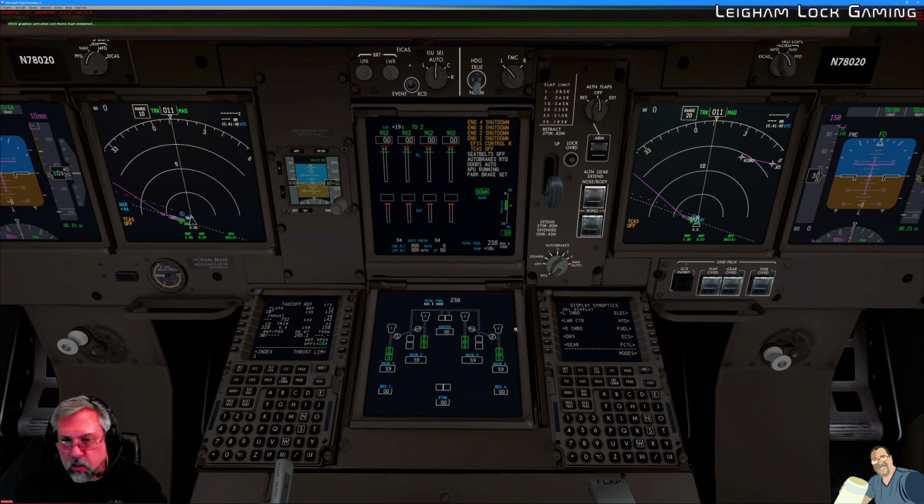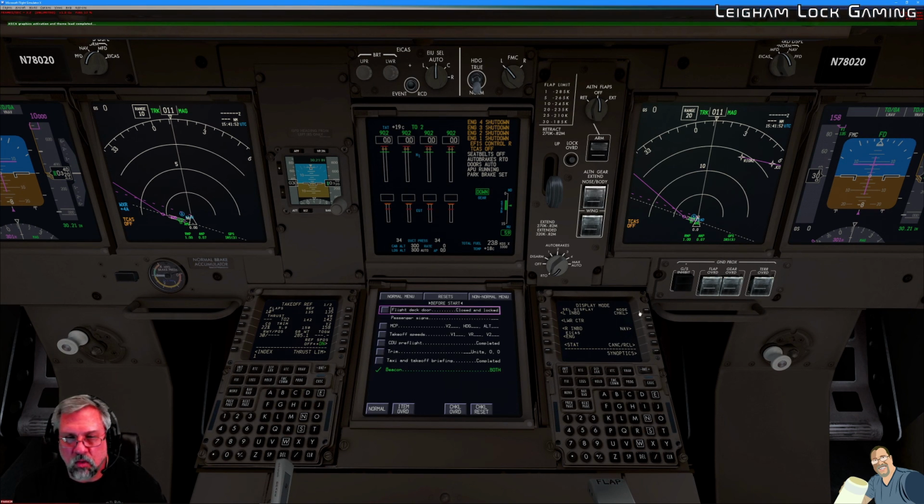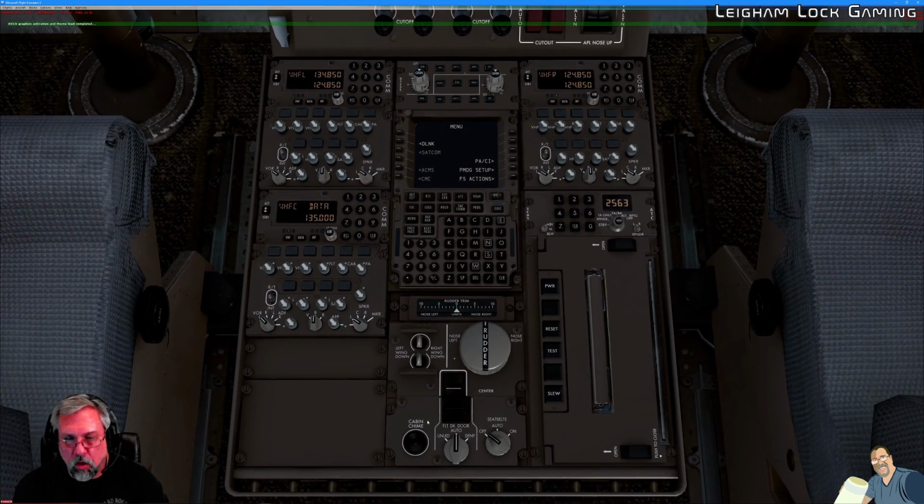So, before start checklist. Flight deck door closed and locked. Check. Passenger signs. No, we have not done the passenger signs. So down here to our passenger sign, our seatbelt indicators should have been in the on position. Now they are set correctly.